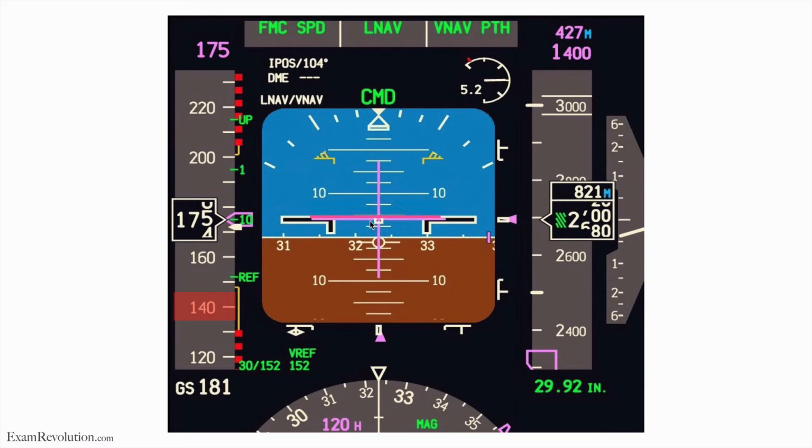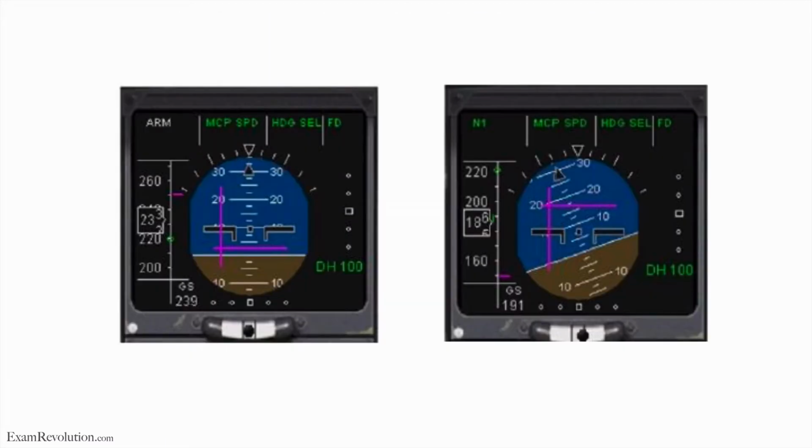And then if you, for instance, have brought the nose up too far, well, the bar would start going down again, and that means you must lower your nose, because otherwise you'll be flying too slow, right? You'll be flying below 140 then. So the bar will always show you how to fly 140. That's what the flight director does.